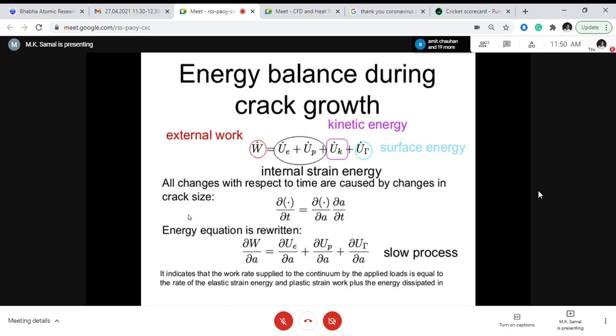Okay. So this is correct, but there are other things to it. See, one is design by stress. For example, when you do the design of a shaft, a beam, or any component, a pressure vessel or something, you see how the stresses are coming because of the applied load. Then you apply different theories of failure, right? Like the principal stress theory, the von Mises distortion energy theory, the stress criteria, etc., to check your failure criteria, and the failure can be either yielding of the material or brittle fracture.